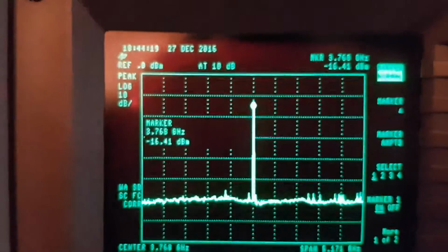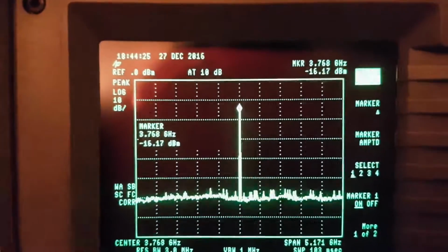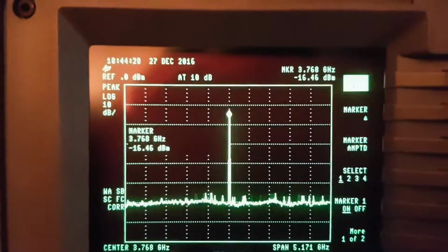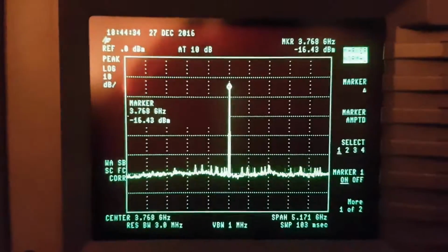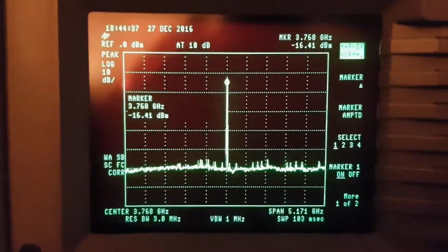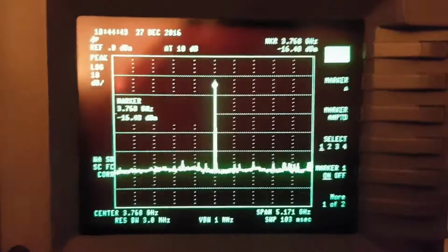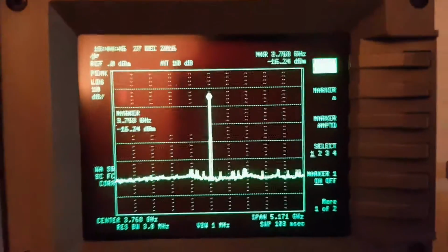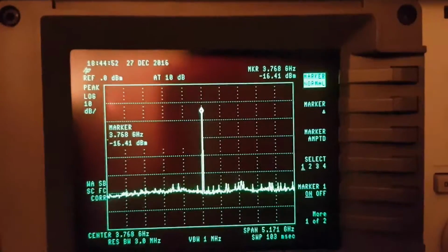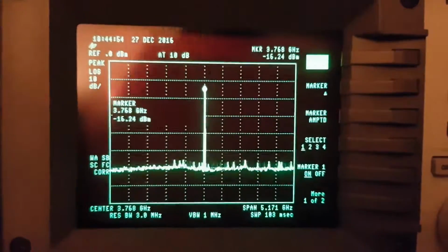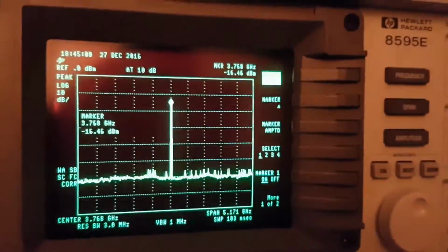Now the TR4131 gives the output of the second LO as being greater than minus 5 dBm, so I'm not sure whether this should be the same, as I don't have any details for the TR4131. But it looks to me as if the first and second local oscillators are within spec. I could be wrong, but I'm thinking they're working okay.